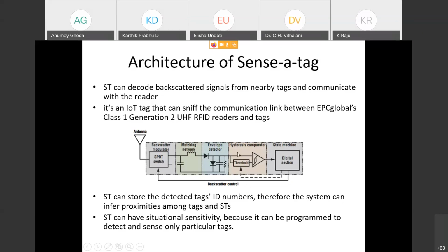That's it. Now suppose after the envelope detection, the distance is 4 meters. Threshold is 10 meters. Now suppose the digital signal that is given out is 5 volt. 5 volt is mapped to say 1 0 in the digital section. That means from 2 volt to 5 volt it is mapped to 1 0, and 1 0 means what? Brake will be taking control.